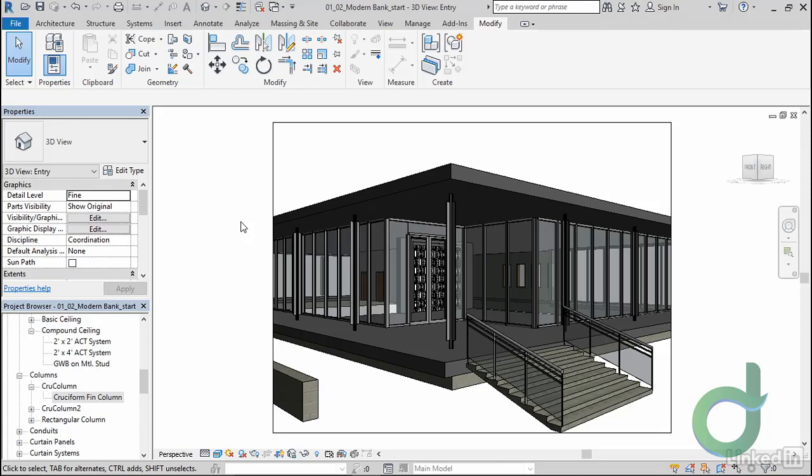16-sided, faceted columns that have flat spots my steel can join onto, so I get a clean joint between the flat steel and the round column. And then there's enough sides, 16, that a 4-inch column, as seen from a view like this, or even a close-up view down here on the slab, is still round enough that it'll look round.